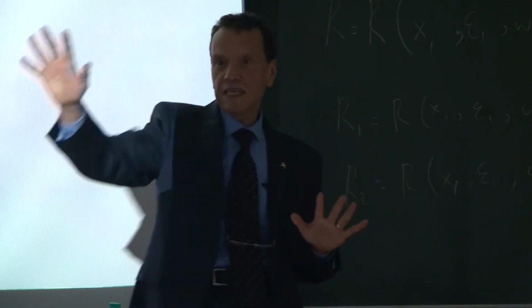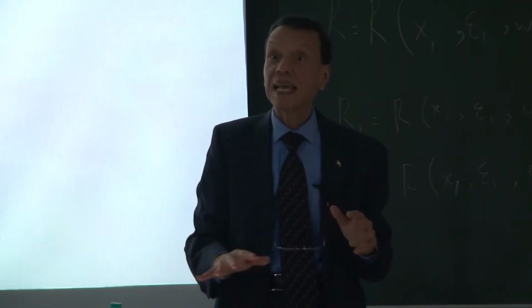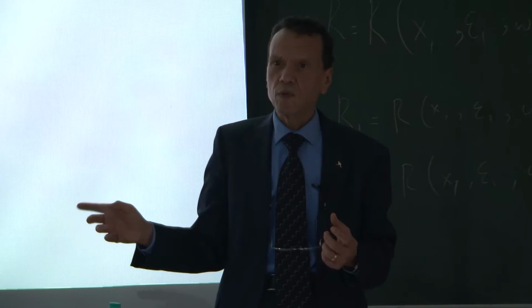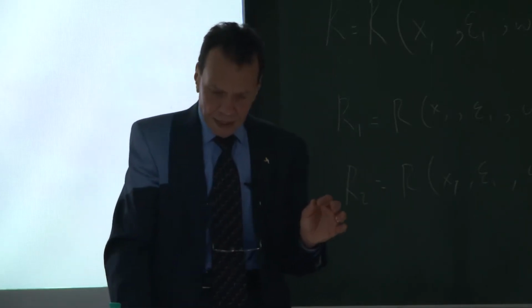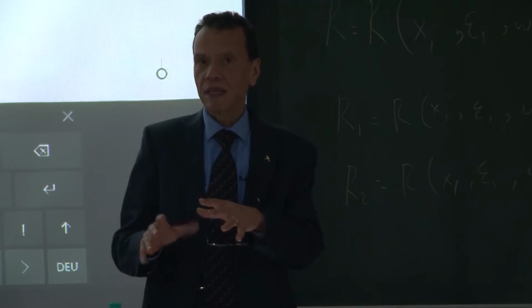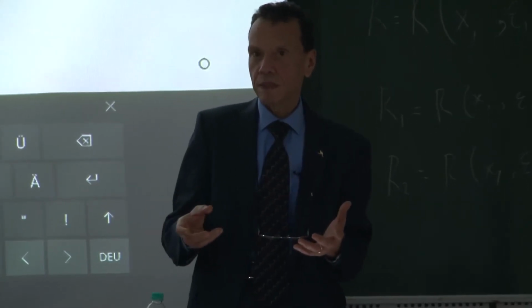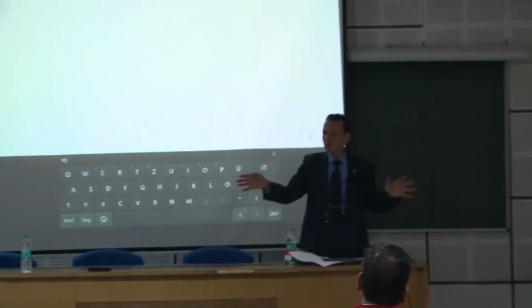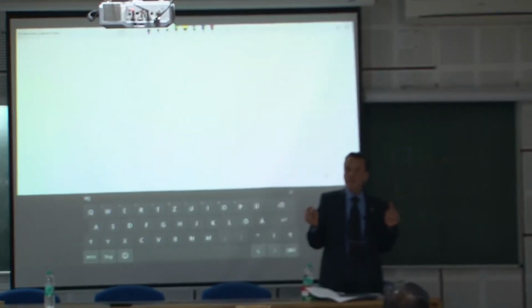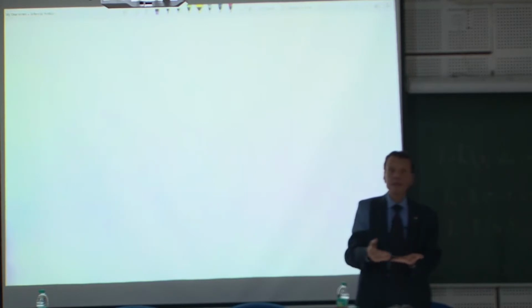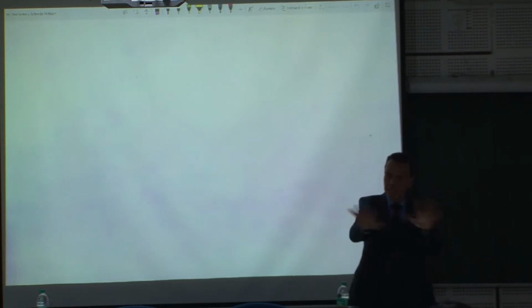Where you say, okay, I have electric field distribution, magnetic field distribution, and I can define permittivity and permeability. Look, in our model here, we assume that we could smear out the microscopic properties into a macroscopic property. So, as you see here, I consider everything continuous. I didn't go into the level of atoms. I didn't go into, as I told you, absorption. Again, when I calculate absorption, when I calculate epsilon r, epsilon r dash and epsilon r double dash, I calculate the macroscopic, and macroscopic means I smear out.